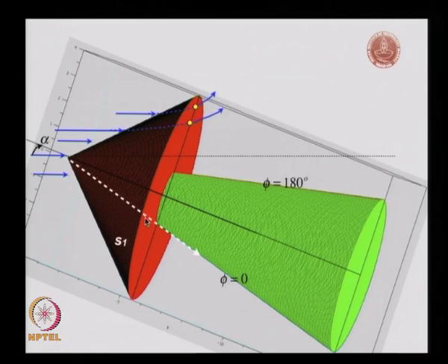Other than that, let's say at this particular point, since the bottom of the shock and the top of the shock are different because of the shock wave angle, this is the stronger part of the shock. So at the end of the day, when my flow encounters the shock and goes across it, it will encounter an entropy change of S1.